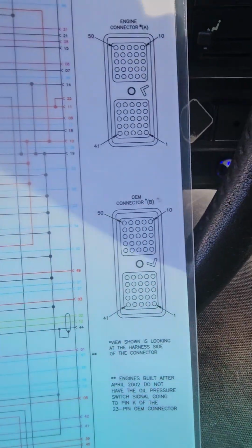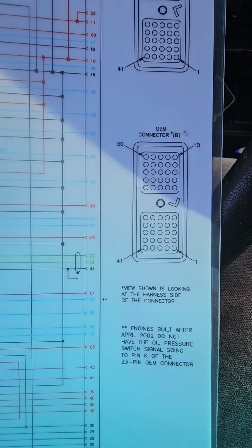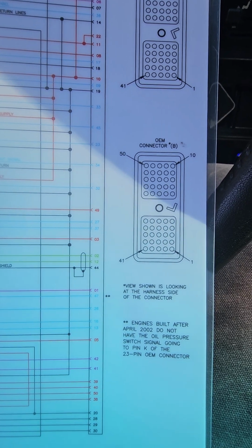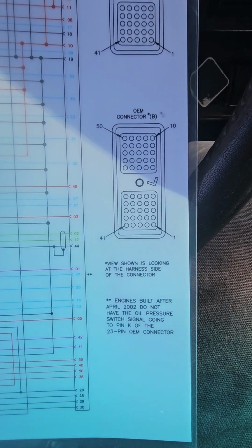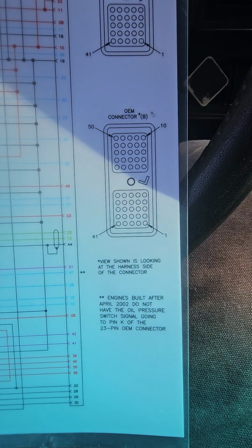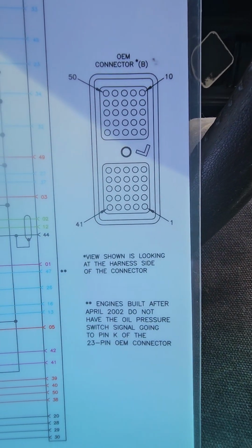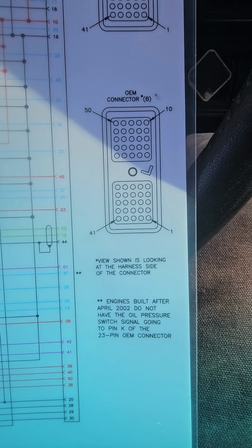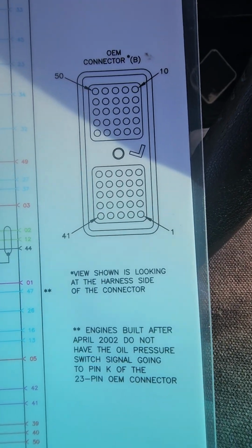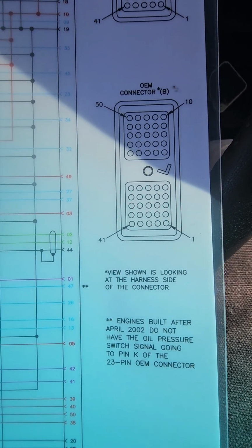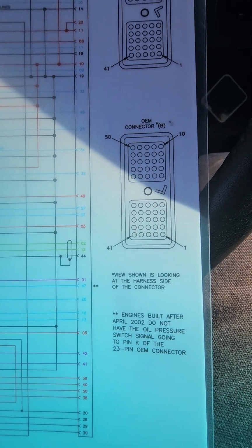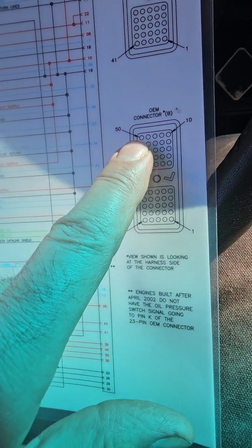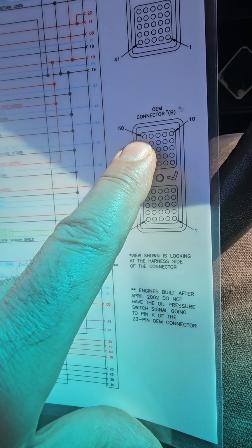So when I had the computer codes and they were saying low voltage signal to the lift pump and all that, and I could hear the motorhome wanting to die, it's just stumbling. And I'm looking at my scan tool, I'm noticing that the battery voltage on the scan tool is lower than what I measured at the battery when I thought I was checking for bad grounds and battery connection. So I hopped into the engine compartment, I pulled the plug, and I tested position 50, and I had battery voltage, and that was accurate.